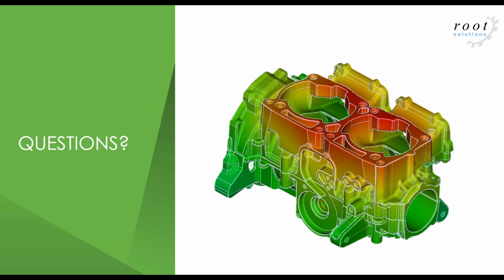A good example is a complex crankshaft analysis that we did. We were within 2% accuracy of what you would get with ordinary Creo Simulate. However, the difference was the time. It took 3 minutes to process in Creo Simulate, and it took 3 seconds to process in Simulate Live, which is a pretty big jump.